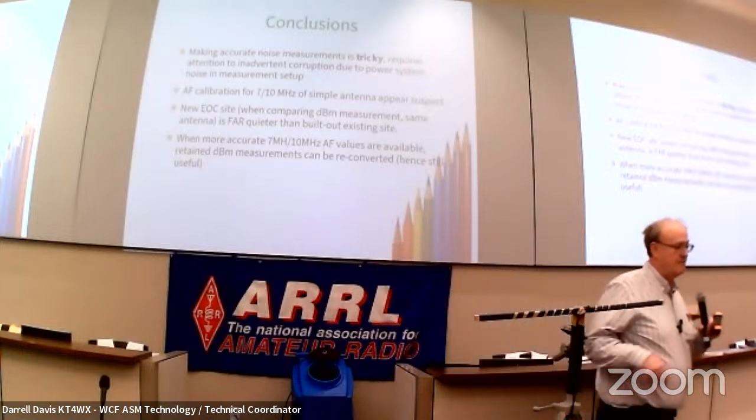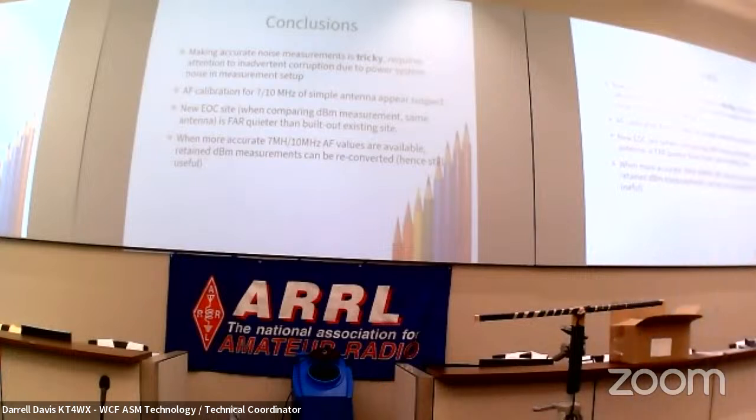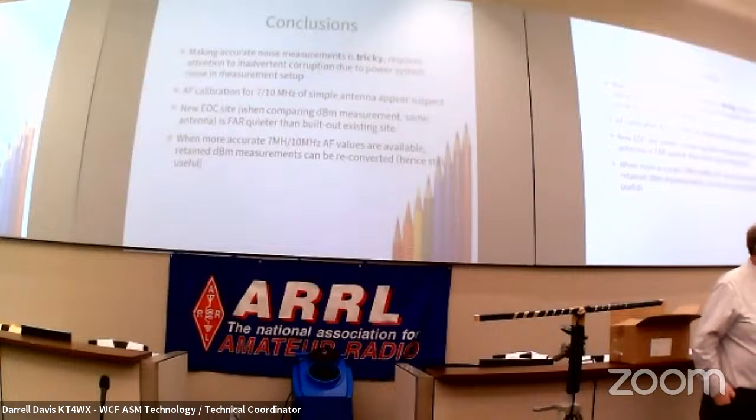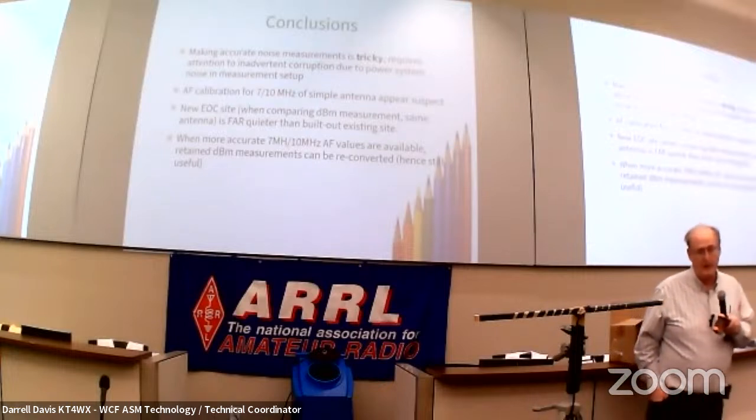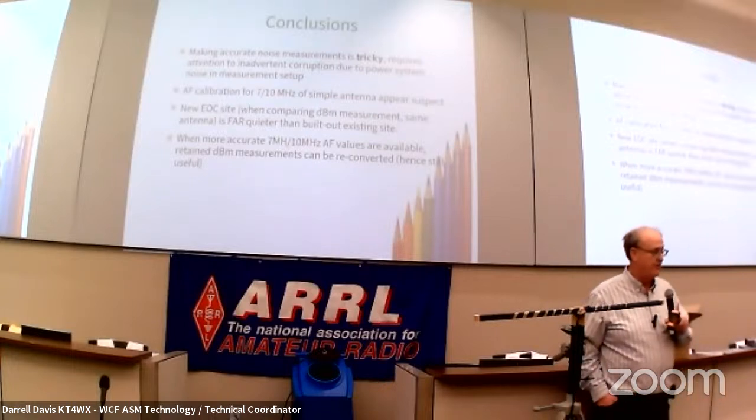The second thing is you can filter on the output, and there are consumer devices that can be put on either the input or the output. I found them. They're like $100 each, and there's not a lot of them, but I found them. And so I documented this device from Tripp Lite, this device from whoever the other UPS manufacturer is. They make some filters. They're not great, but they do work. The industrial filter that we use is the MIF-23.